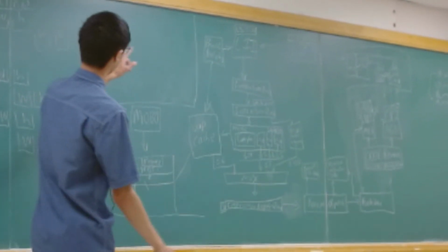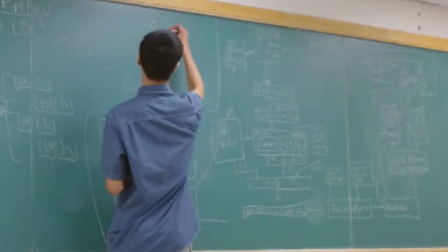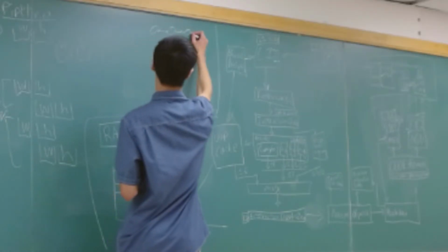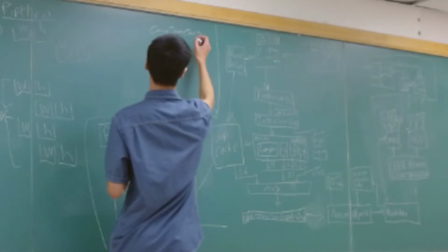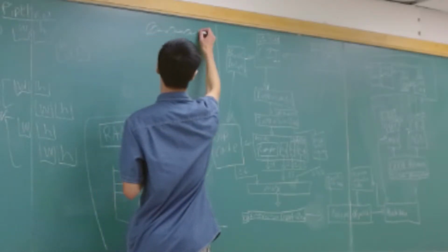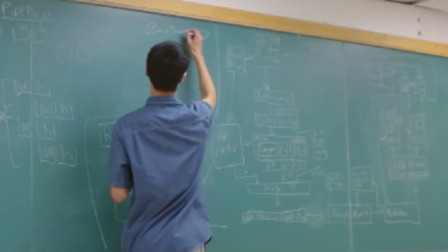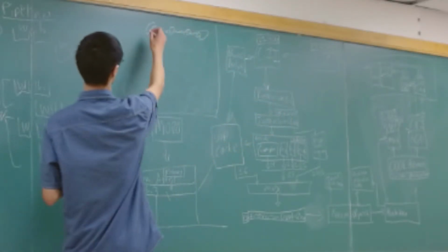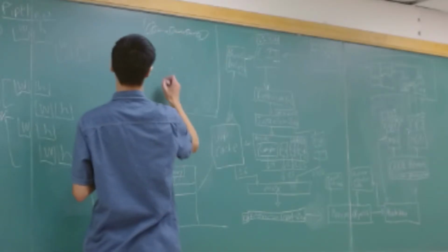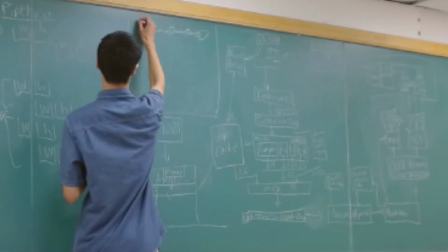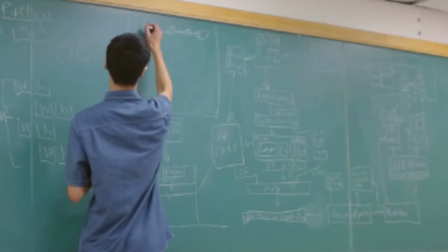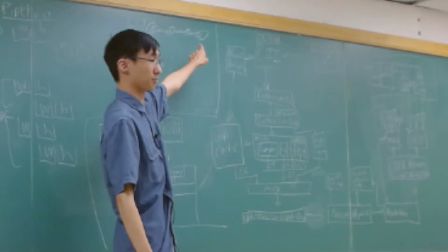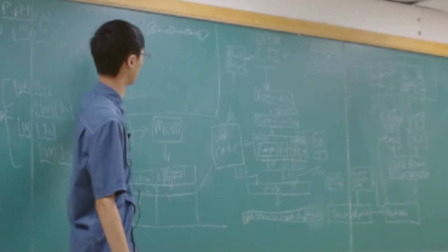You will take one of those saturating counters, right? You'll take one of those saturating counters where you can go forward and backwards on each set, whether you take or don't take. And you'll label them taken and not taken for each of those. And you'll copy that down, and you will index them using the branch history. So I'm not going to draw all of them, but let's say 0, 0. So you haven't taken the branch twice in a row. That means you use this predictor, right? That's a branch history style prediction where you use saturating counters.